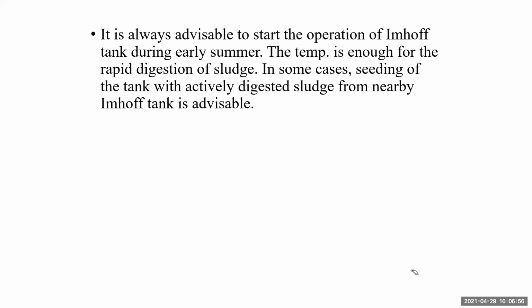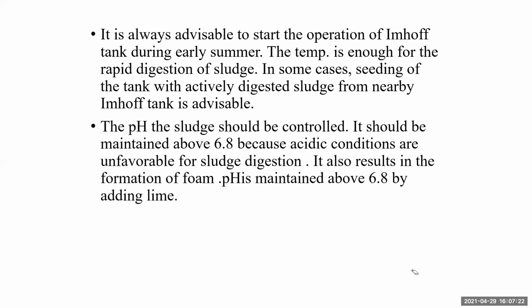Now, as far as the working of the Imhoff tank is concerned, it is advisable to start operation of the Imhoff tank during early summer. Why? Because the temperature is high enough for rapid digestion of the solid sludge. In some cases, seed or actively digested sludge from a nearby tank is added. It is advisable because it will speed up the process of sludge digestion.